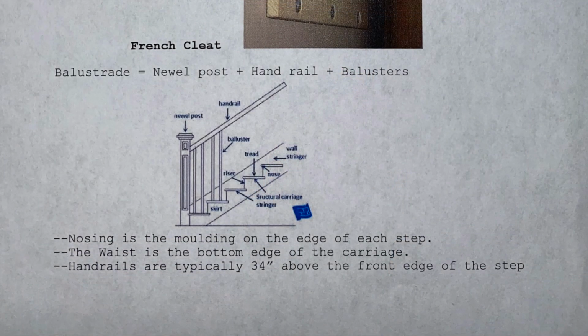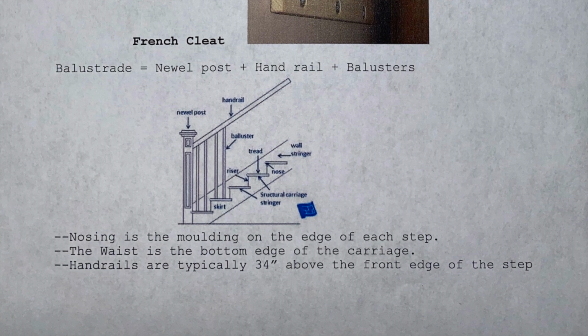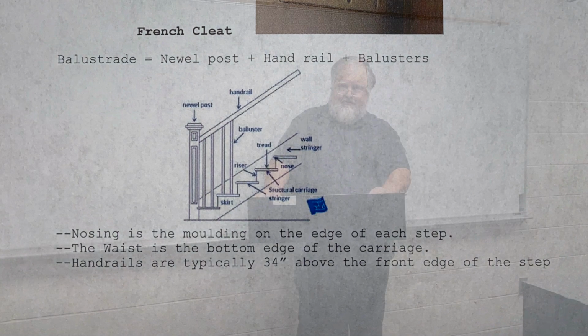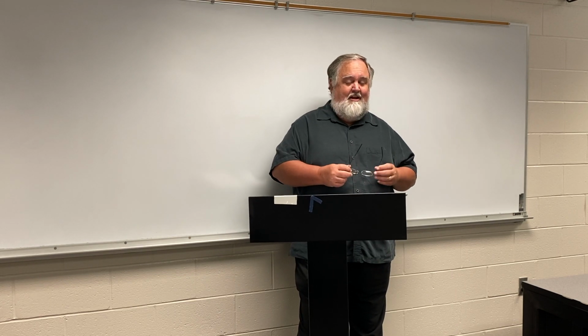Okay, lastly is the handrail. First of all, there are several parts of the handrail. The newel post is the part of it that gets its strength at the bottom. The handrail itself, again, in America, is 36 inches. In other parts of the world, with shorter people, it's less. But in America, 3 feet is the standard handrail height. I'm sure that you've been around rooms where you reach, just like the doorknob, you reach your handrail and it needs to be right there, and it's down here or it's up here. You're like, whoa, this is a little off, but even an inch, your body knows, right? But 36 inches is the standard height, and again, that goes from the nose up.